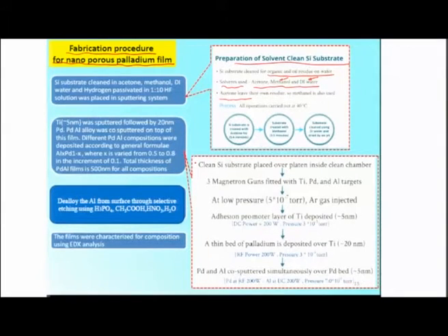And then what we do is we use a deposition process called sputtering, which I think I have discussed in some of the modules earlier. Before this sputtering, we also passivate the surface by hydrogen passivation techniques, where we dip the surface in a 1:10 HF solution, and then we place the passivated surface on. So there are a lot of hydroxyl groups now on the surface of the silicon, and we place this in a sputtering chamber. In this particular module, we are using titanium as an adhesion material.